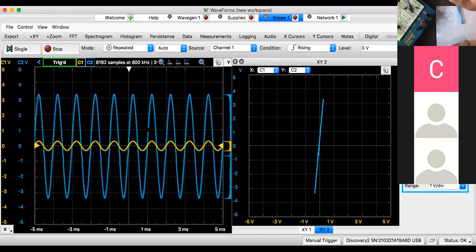If the input signal is too big, it will saturate on this side, so the input signal has to be smaller than 300 milli. If the input signal is stronger than 300 milli, it will reach a flat plateau right here. And the bottom is the same thing. So you will see the saturation. You also call it the cutoff. You have a positive cutoff. You have a negative cutoff. Right now, there's no positive cutoff, no negative cutoff. Everything looks good. So that's issue number 1, saturation.